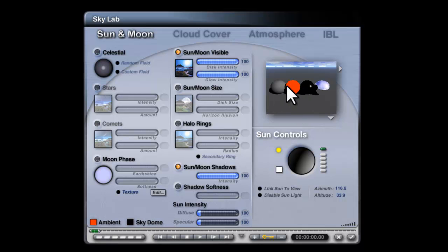You can see that this material's responded immediately, but it's just a circle in the render. There's no three-dimensional form. It doesn't really tell you it's a sphere. So the ambient was put in there to make up for the fact that on slower computers you couldn't produce very high quality lighting, because that meant having to include a lot of light sources or use global illumination methods, which we'll touch upon later on.